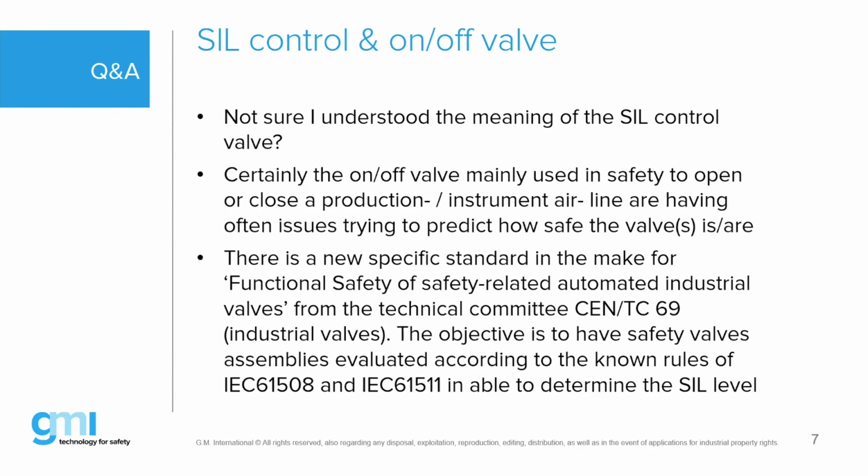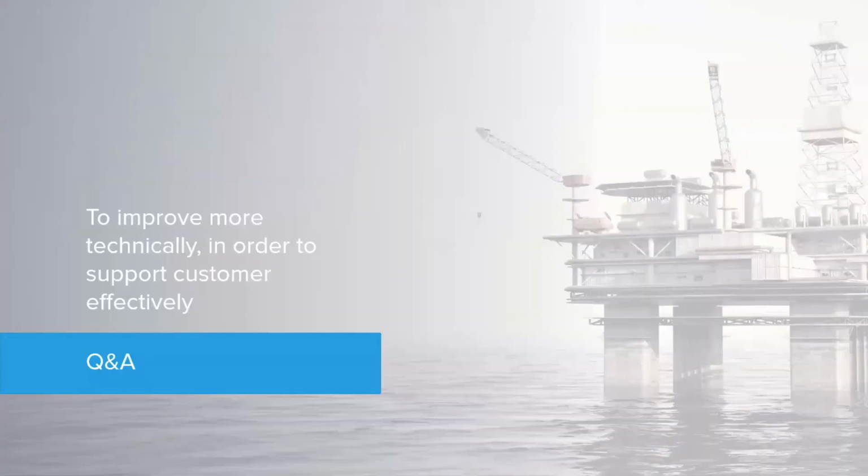We can certify the functionality from end to end, from sensor to final element. That we can certify and give it a SIL X. But if you take your SIL 3 safety relay out of the equation, your loop will not work anymore. It is an integral part of my loop functionality. In order to build a loop, to keep it easy, I will seek, as an engineer, all SIL compliant devices, because then my job is easy.